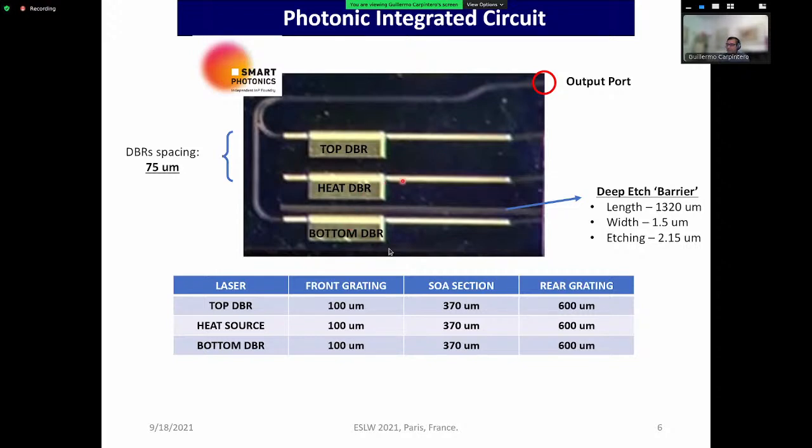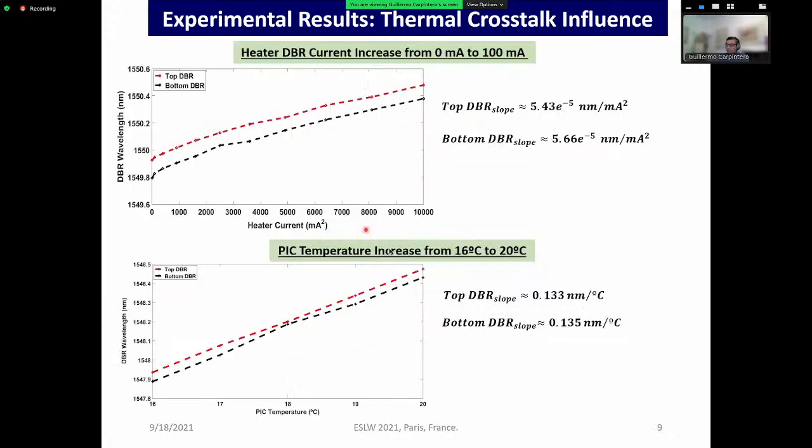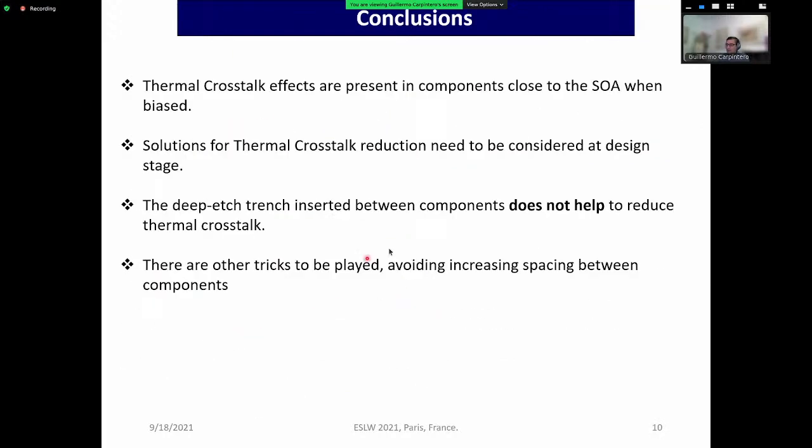And actually, the other trick that we can play is that we now have this metal on the top surface, so we can use it as a thermal radiator. This is to extract the heat in between and then create a barrier by sinking heat using metals on the top of the surface. These are the current tricks that we are analyzing in this chip. Also, we have to check the position of the chips within the die.